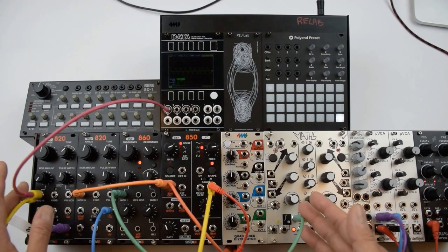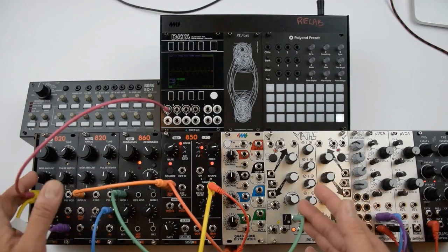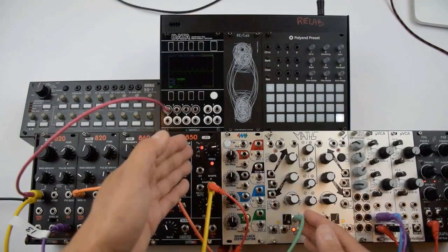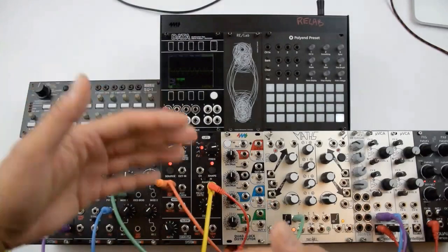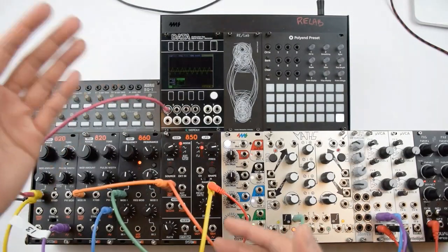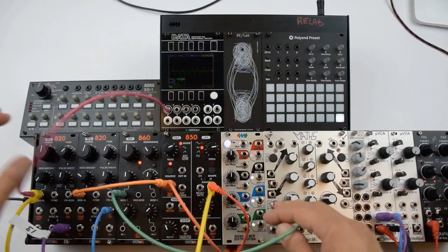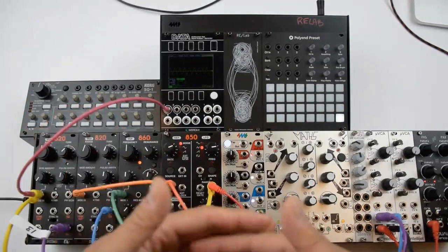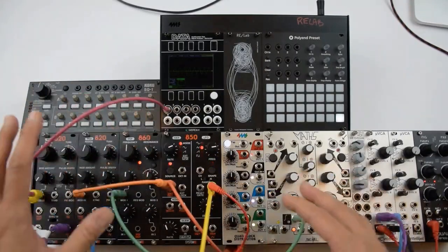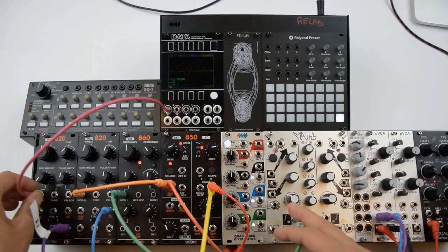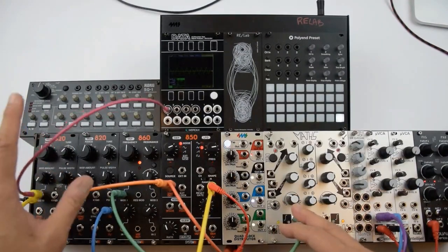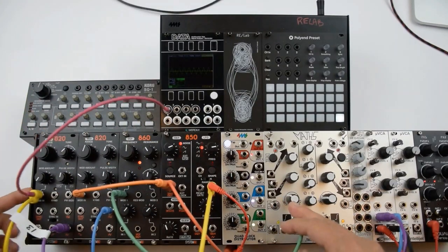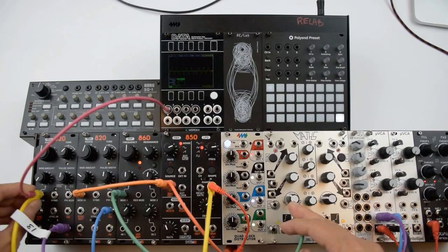Now, if we remember that in Eurorack format, a 1 volt change equals a 1 octave change, then a low frequency oscillator sweeping between, say, 0 volts and 5 volts, if we simply plug that into an unattenuated pitch modulation input, is going to sweep through 5 octaves of frequency of our oscillator, which is not typically a very musical effect. So to create a gentle vibrato, we need to limit the range of the incoming LFO. And luckily on this particular oscillator, there is an attenuated input for modulating the frequency.